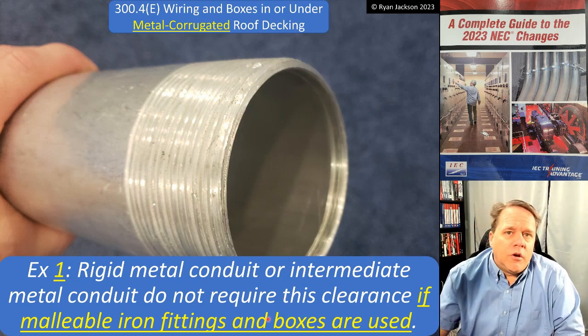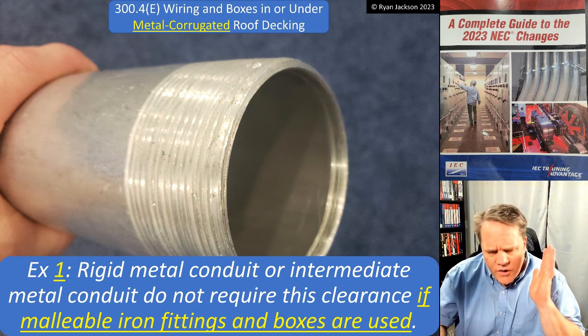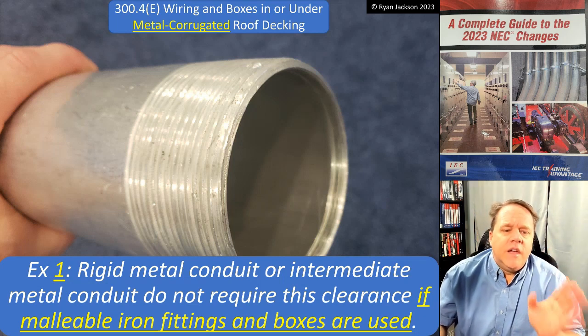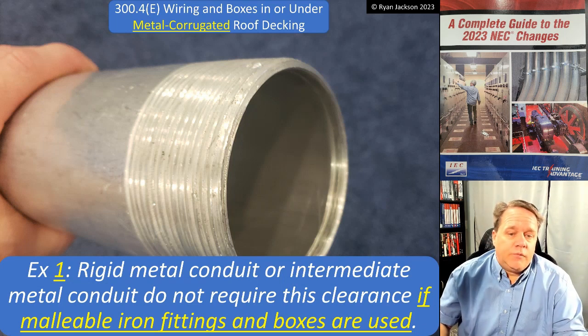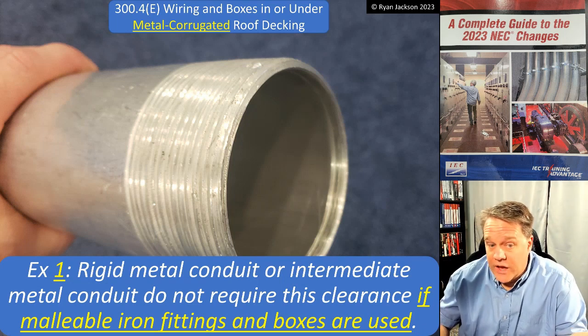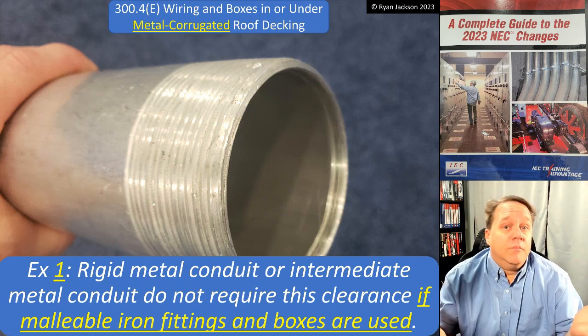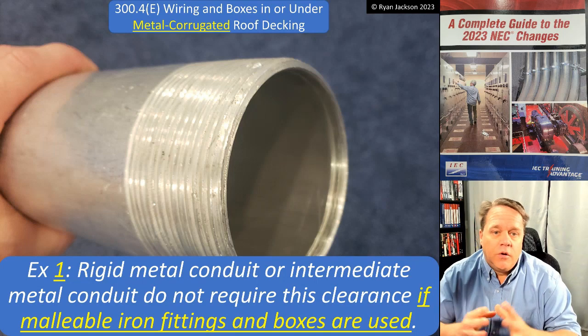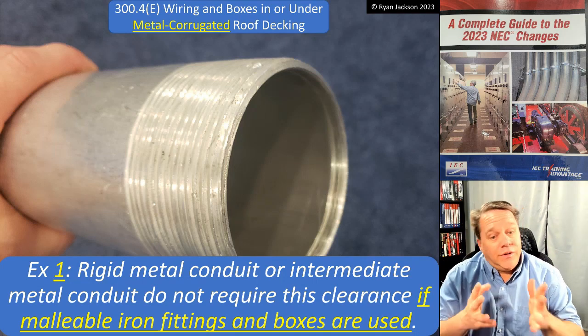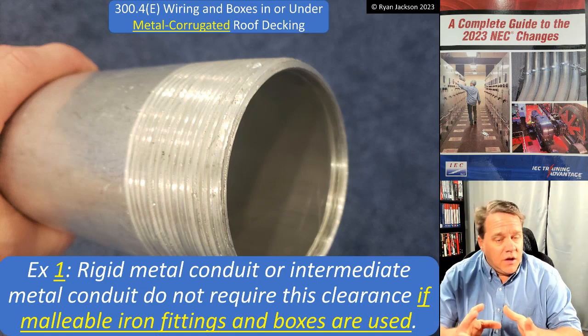So rigid metal conduit or IMC conduit does not require this clearance if malleable iron fittings and boxes are used. So we're clarifying that if we were using aluminum fittings, for example, that wouldn't be allowed because aluminum, of course, is not nearly as strong as steel. So I don't know that anybody is really taking advantage of this exception.